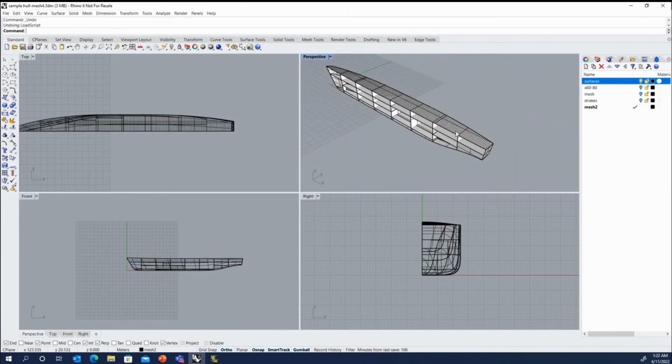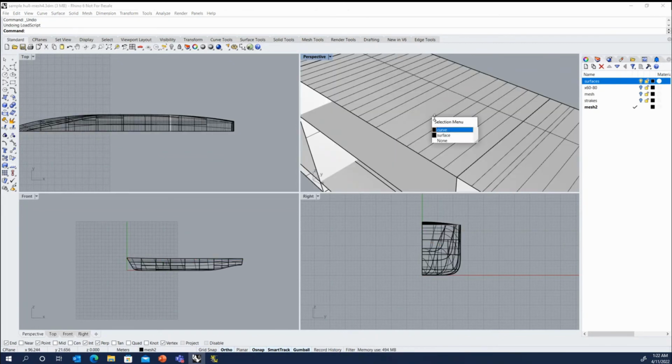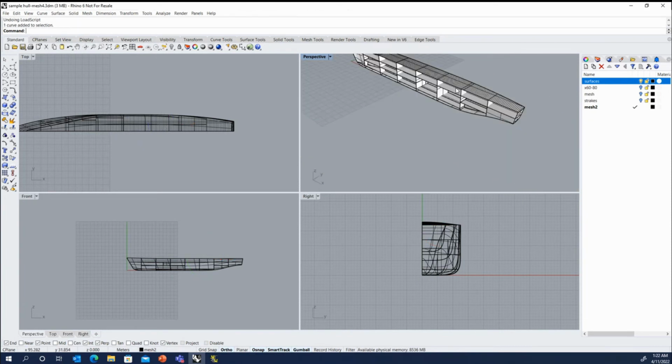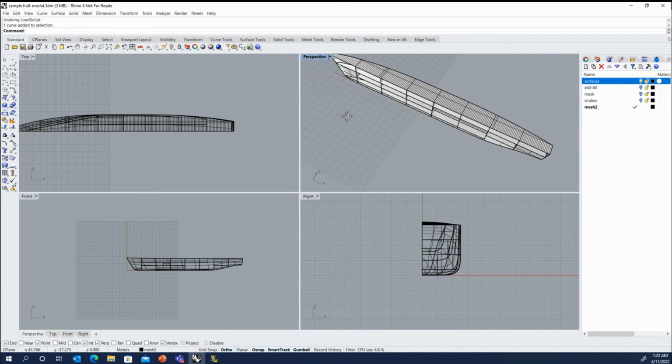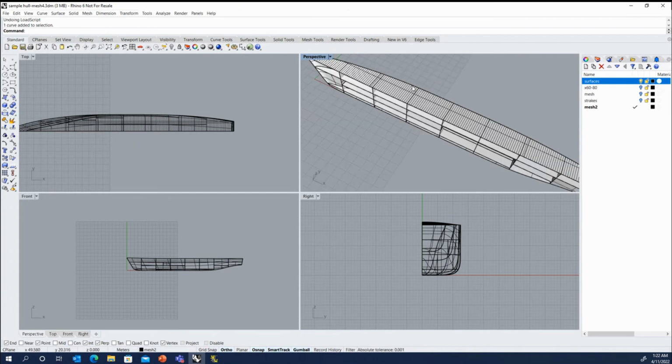So let me undo those commands for the script. And now we're back to the original curves, single segment here. And we'll use the contour method to generate the points here. And let me show you that range option on here, running contours.